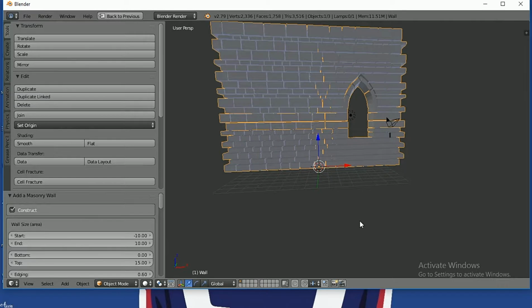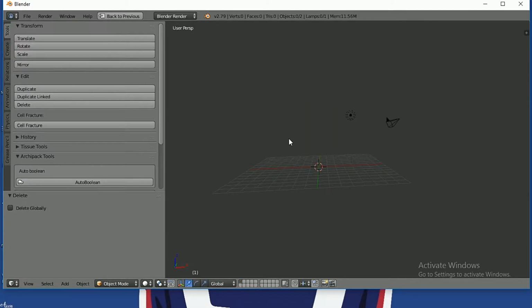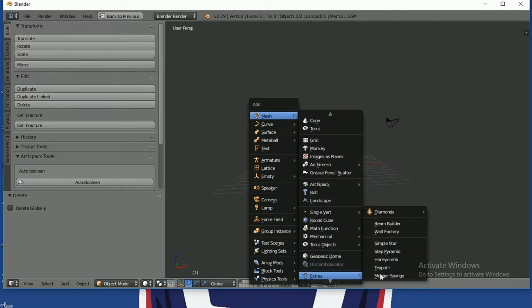The first thing that you have to remember is don't even change its position while adding. After adding it, just keep it as it is and look here. Because if you do any slight change here, these options won't be available. These options are available only at the time of adding the walls. I'll show you an example. I'm moving it and voila, they're gone. Now to get them back, I need to add it once more.